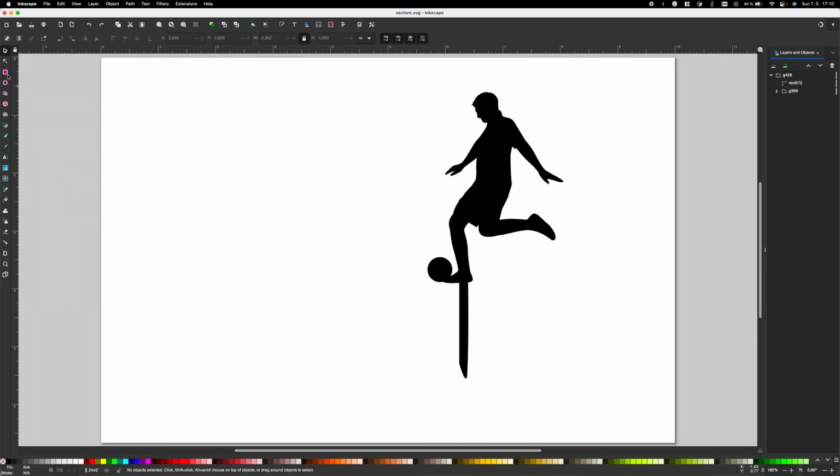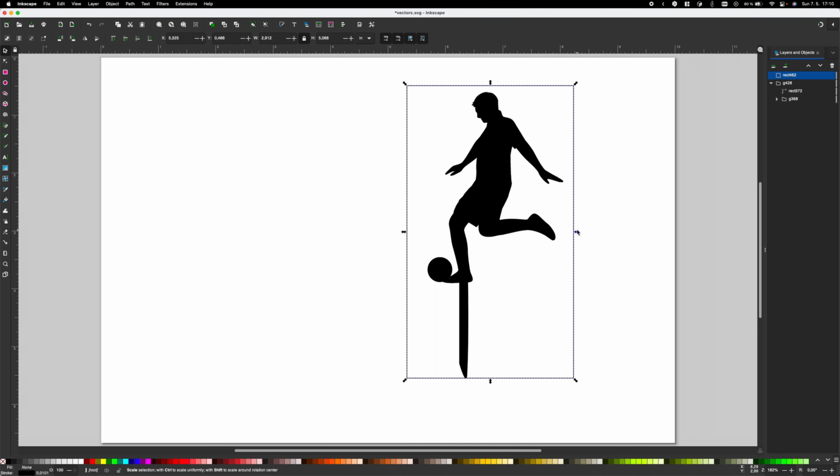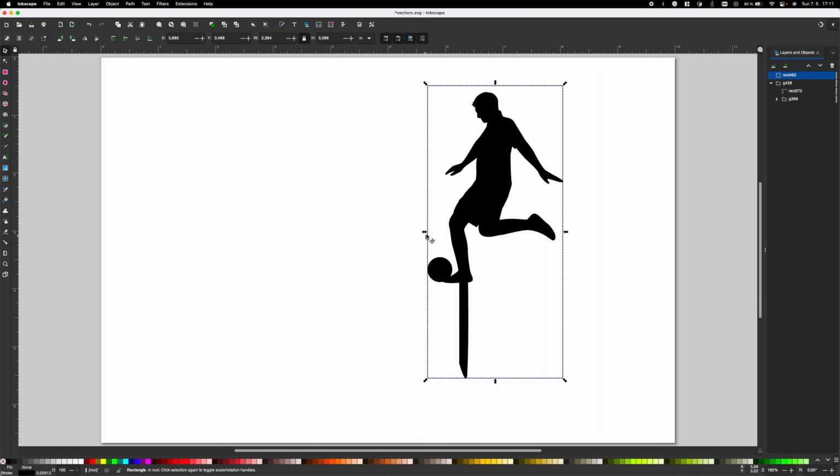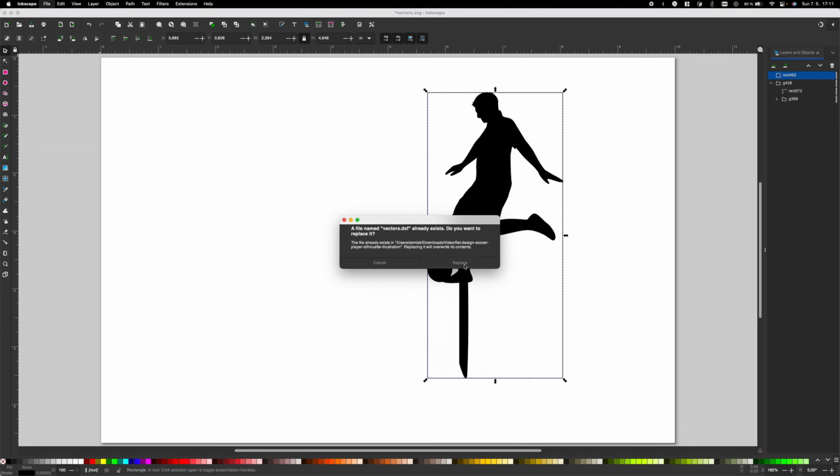Just draw a rectangle around the model without any infill. Set its edges as accurately as you want to be able to define the dimensions of the final model. The fact that the rectangle interferes with the image doesn't have to bother us at all. It is an object on a different layer and does not interfere with our image. If we are happy with the image, we can try saving a copy of it again in the DXF format. This time we can ignore the errors.